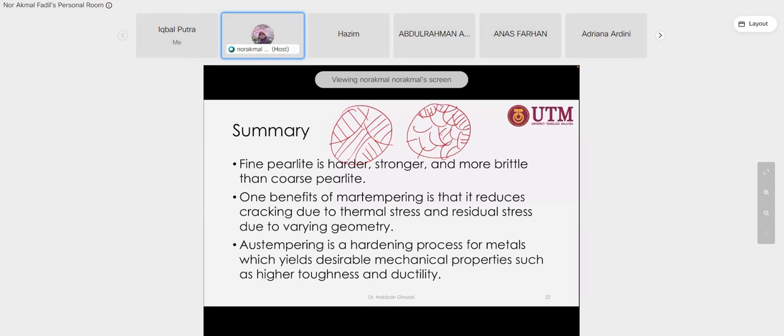They are all pearlite. Okay, so a finer microstructure is stronger, because of the grain boundary. Always remember this. At this point, you can utilize the benefit of grain size without changing the type of alloy.